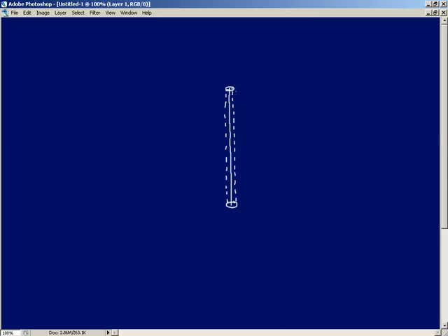So this may make you wonder, well, why didn't you use a tube to begin with? Because that would have just been one node. Well, we're going to be reusing this line right here. This is going to work out really well as a line that we can use to copy rungs from the actual ladder to. And we'll talk more about that when we get to that video. So after we sweep this, we've got a tube.